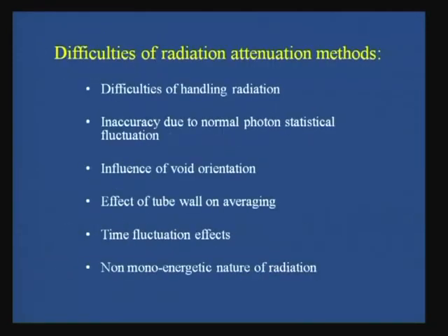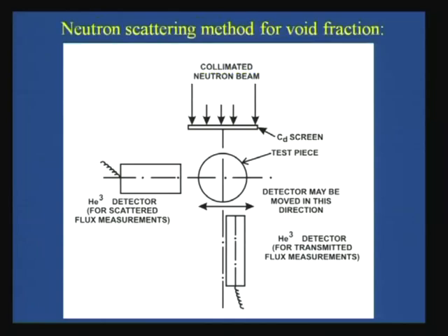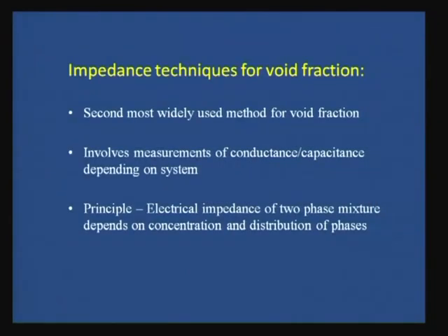So this technique is the second most widely used method for void fraction measurement. It involves the measurement of either the conductance or the capacitance depending upon the system. If we are operating at a higher frequency, then capacitance is dominating. In that case, the method works on the difference in the dielectric constants of the two phases.